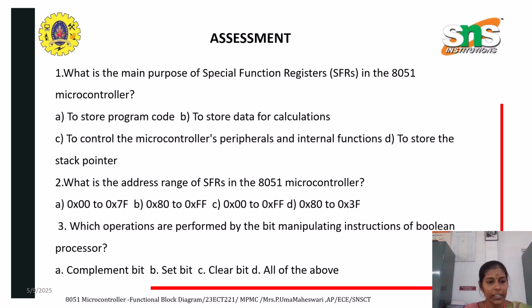In order to effectively monitor and control the 8051 microcontroller, the special function registers are tremendously useful, on the transmitting side as well as the receiving side. As we have observed from the internal RAM structure, the address space allocated to the SFRs ranges from 80H to FFH, a total of 128 memory locations.